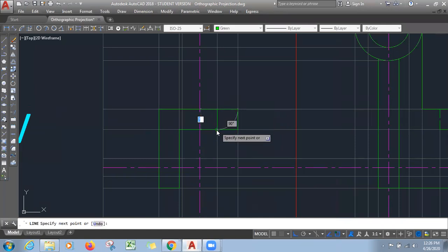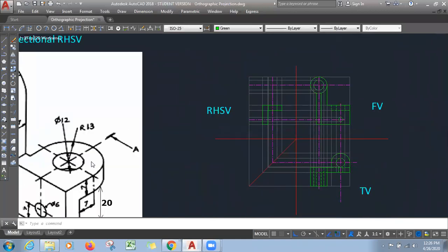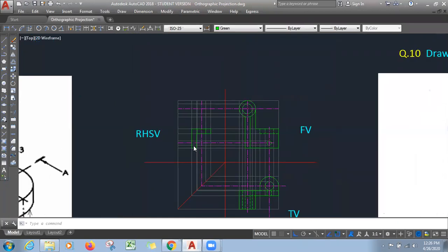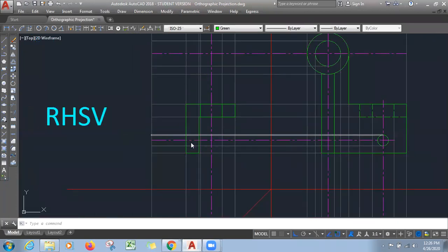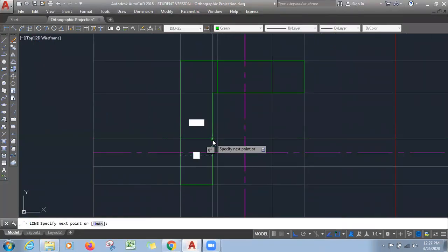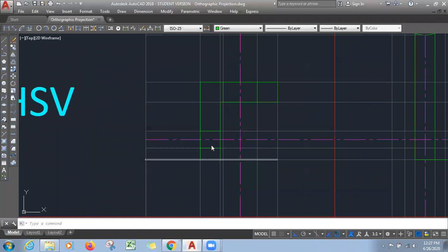We already have projection lines, we can draw dotted lines there. Similarly dotted lines will be for this circle. Again, this circle cannot be seen, so in this direction this circle will be shown by dotted lines here. The levels we already have, this one and this one. So again at this place, these lines are again dotted lines.